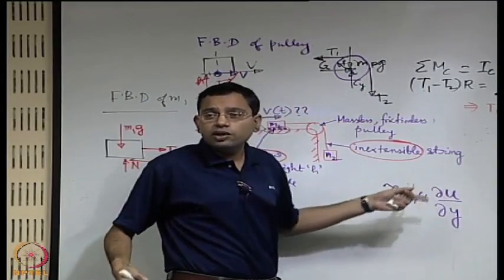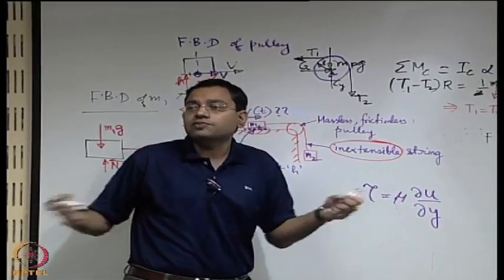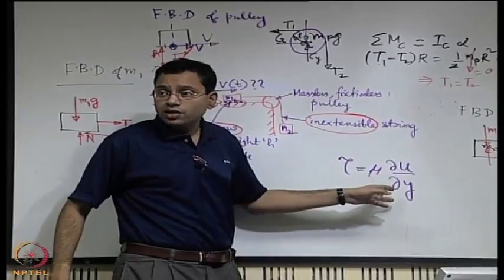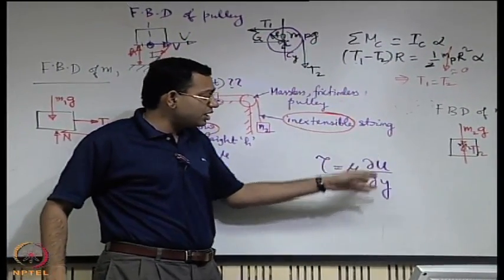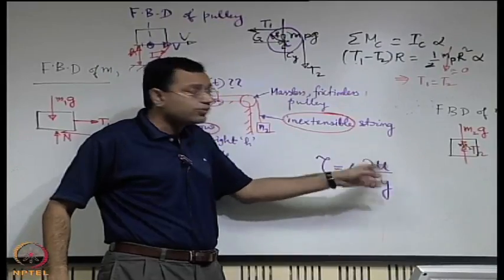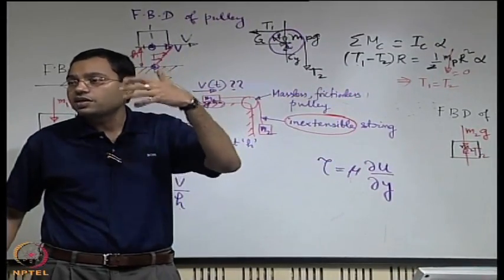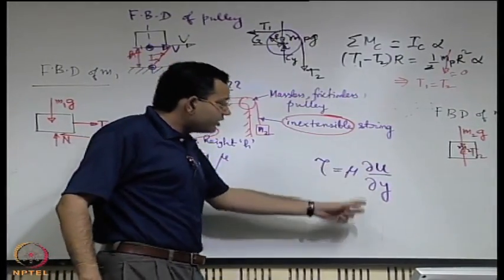If you write du dy, which we wrote for the first time just for simplicity in understanding, it is in general a partial derivative. It assumes that there is only one component of velocity, and the partial derivative comes from the fact that that one component of velocity itself could be a function of many things, x, y, z, time, and it could itself be a variable.